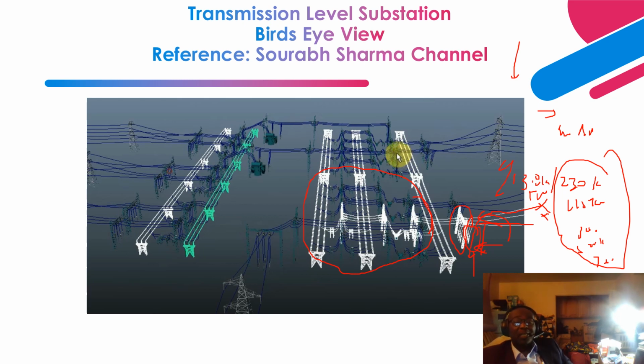Once it senses that overvoltage condition from a lightning strike, basically it changes from a high impedance operating characteristic to a low impedance, and basically shunts the discharge amps, kiloamps to ground to protect the equipment that is in this switchyard. Okay. So this transmission line network, let's say we have 765 or let's say 345 comes in here, right?